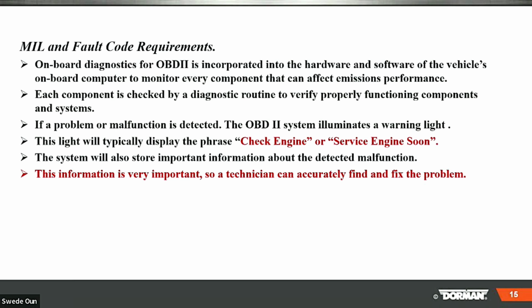You've got the MIL and fault code requirements. Onboard diagnostics for OBD2 is incorporated into the hardware and software of the vehicle's onboard computer to monitor every component that can affect emissions performance. Each component is checked by a diagnostic routine to verify properly functioning components and systems. If a problem is detected, what's going to happen, guys?